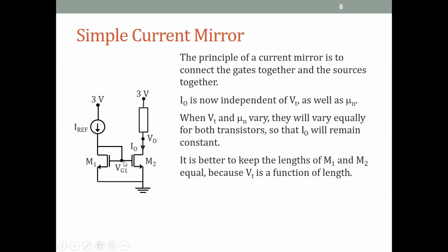So now one can imagine that I can connect this VG1 to 100 different NMOS transistors which need to act as current sources. Instead of building a current source by providing a DC gate voltage to an NMOS, I will just apply this gate voltage wherever it is needed for the MOSFET to be a current source. And one achieves different values of currents, because if I have 100 different places where I need current sources, of course each current source will need a different value depending on the design of that specific amplifier or whatever.